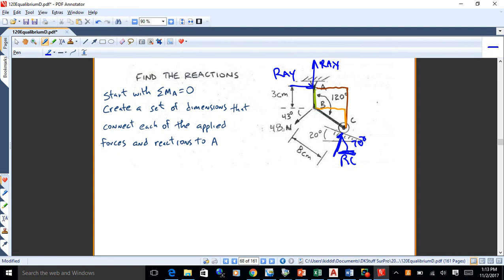So don't get hung up on the picture in front of your free body diagram. Just get those forces on there, figure out what we're going to take moments about, and connect that point to the forces with nice clean XY dimensions. That's all you got to do, okay? It doesn't matter what the picture is. That's really irrelevant.